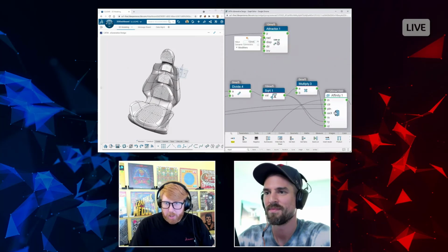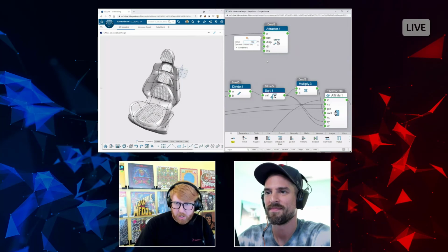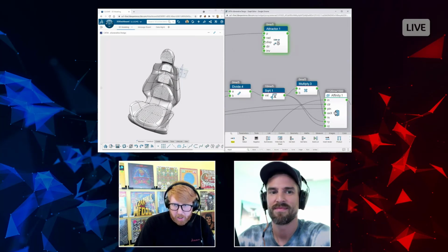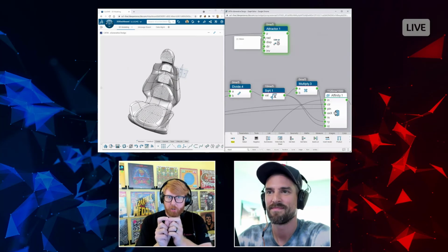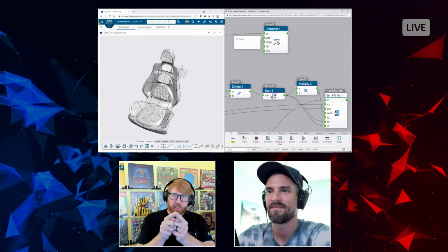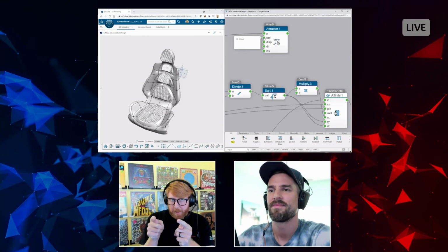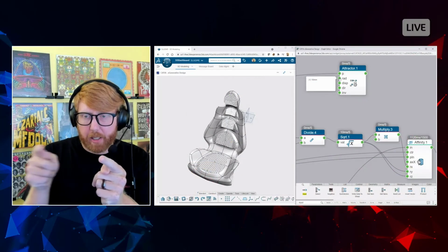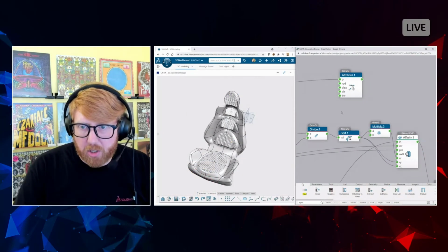So with that point attractor force, I'm taking that center point and I'm going to say within a radius of 150 millimeters, I want you to displace every point. If it's right next to the center point, then I want you to displace it by 25 millimeters. If it's 150 millimeters away, then I want you to do almost 0, and halfway between is halfway, right? So okay. That's basically what it's doing.